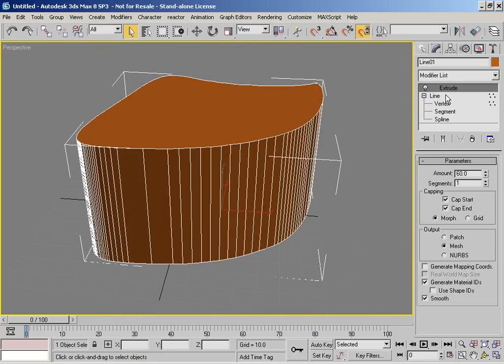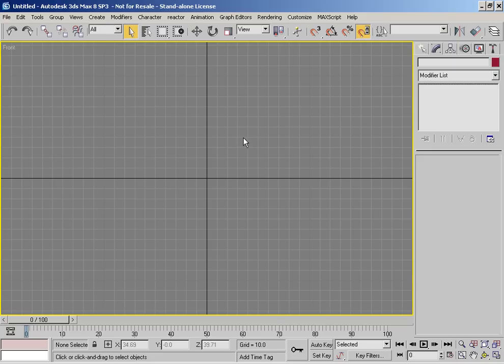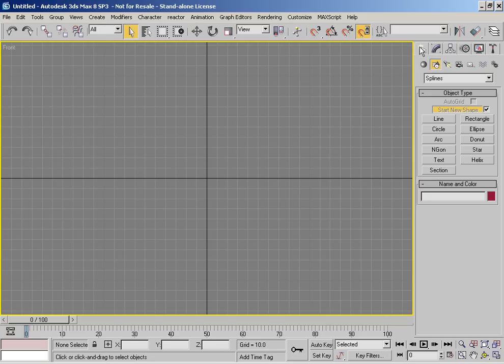An additional method that not many people tend to use is what's called surface tools, and that is using spline cages to create 3D objects. It's like, for example, creating a hull of a boat. You create the main guides, and then applying a modifier, it will simply skin it.